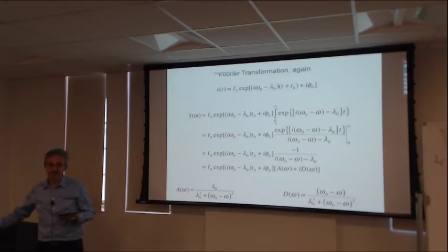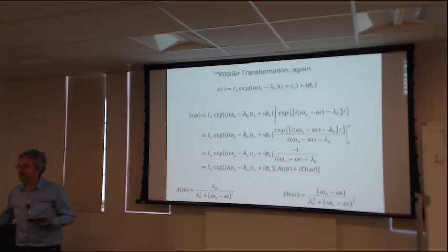To get around that, spectrometers all have filters to filter out the noise outside of the bandwidth, outside of the spectral width that you set. In the old days, these were physical filters built from electronic components, and they would have the property that they would distort the region of the spectrum near the edges of the filter width.